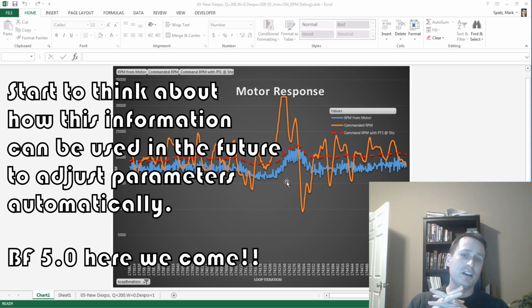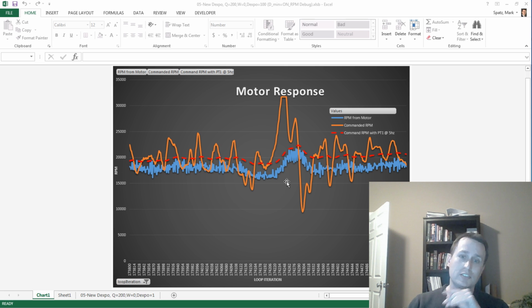Interestingly enough, and Preston Garrison would say this for a while, the motors really act as low-pass filters, and they totally do. You can see in here that the motor command is the orange, and then the RPM data from the motors, and there's some jitter in there just from the signal coming back out. That gets smoothed out in the notch filtering before it goes out to tell it which hertz to be at for the filters. There's a smoothing element on that, but this is unsmoothed, so it's just the raw data, and there's a little bit of jitter there, like I said. And you can see the delta between the two.